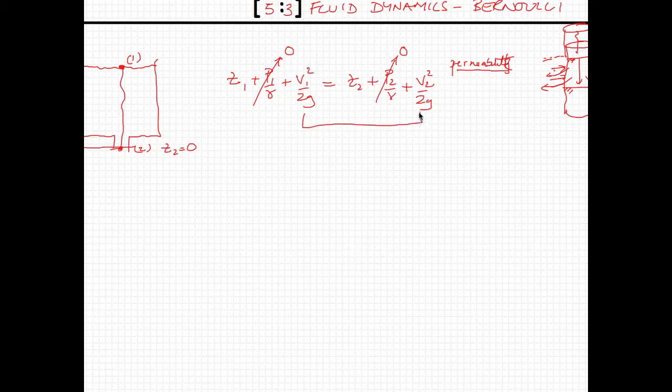Remember when we talked about a free jet, we got rid of one velocity, but in this case the essence of our problem is going to be to include that. So what we'd like to be able to do is note the fact that at this free surface, this velocity v1 is going to be equal to the rate of change of the elevation with time. As time gets larger, the elevation will go down because it's going in this direction, and therefore, since the velocity is always positive along a streamline, we perhaps need a negative sign to represent that, but this is what we'd like to be able to represent. So if we can get a velocity that comes out of the bottom of this tank as a function of time, then we should be able to represent the unsteady case.